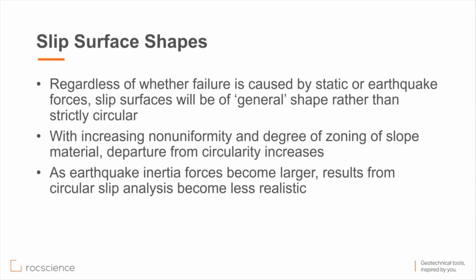because these tend to prevail in practice due to the presence of multiple materials, complex geometries, seismic forces, support forces, all lead to departures from circular slip surface when looking for the critical failure surface. And therefore, we will discuss more methods that deal with non-circular. But almost all of these methods, in fact, all of these methods can also easily deal with circular slip surfaces.